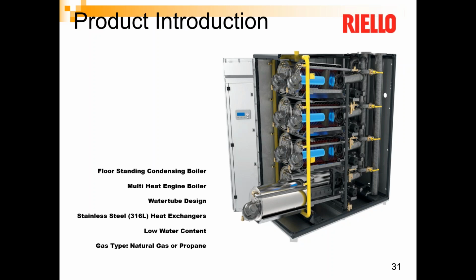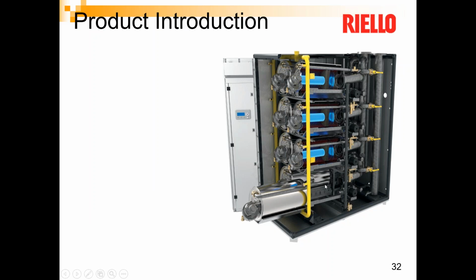If something does go out, like a blower motor, you still have quite a bit of built-in redundancy on each boiler. So you're not having to send a service tech out in the middle of the night to get that going again. You can probably wait until the morning and do it on straight time. You get a guy out there that can repair that one module and get it going again. And even if you ever did have to replace the module, these modules actually slide out very easily on rollers.